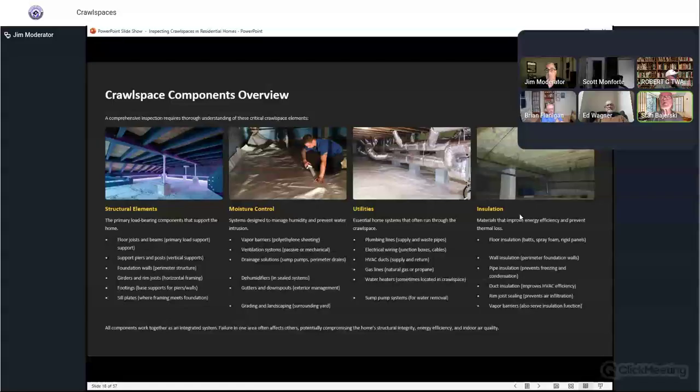And that's why you need to be able to get in there. Now, if you can't get in there and you walk around the house heavy-footed, you may be able to feel some more flex, more bounce than you thought. That doesn't really help in evaluating what's going on underneath, but I would put that in the report to make sure that these folks know you couldn't get in there and it doesn't feel good as I walk through the house.